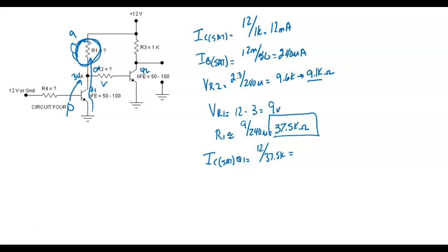And that's what gets people confused because they want to go to 3. But when we saturate it, what do we say this thing drops? We say it acts like a closed switch. It drops 0 volts. So what I end up with is this circuit right here. And this is R2. Well, if I close that switch, that takes that common and puts it right there. Right? You understand?